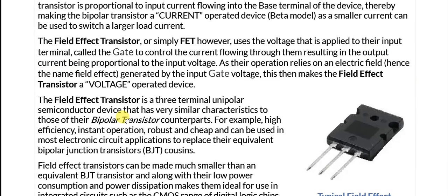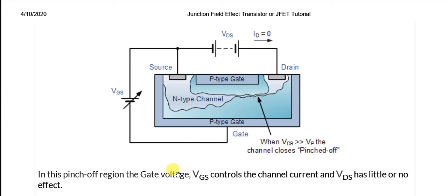The same basic theme is discussed in this case. In the diagram which we earlier saw, the drain current was flowing very fluently, but when we apply the gate voltage over here, which is the highest voltage, let's say -2, these two regions are almost touching, the reverse bias fields are touching each other. Now the channel is almost closed.